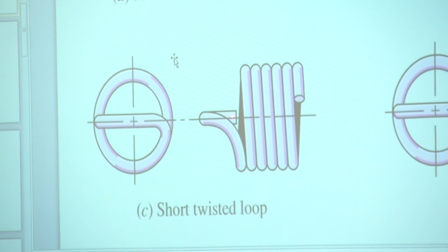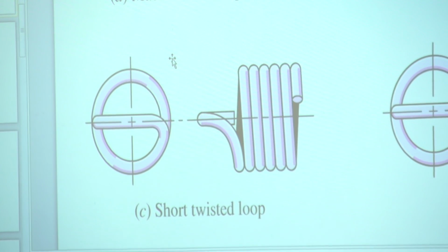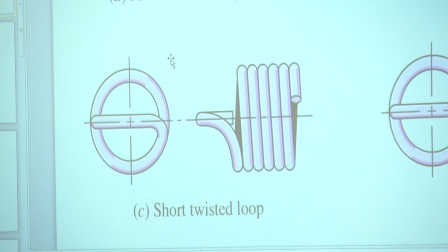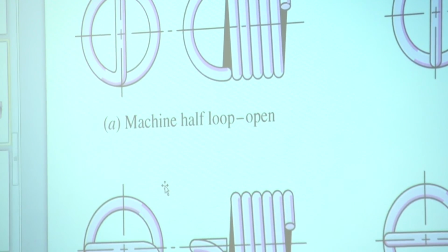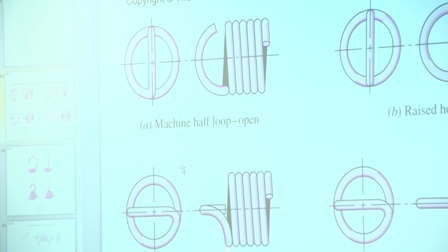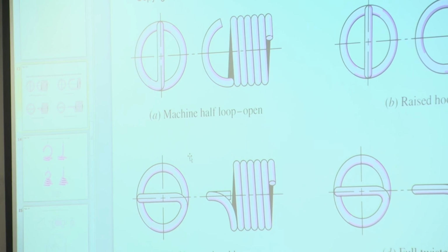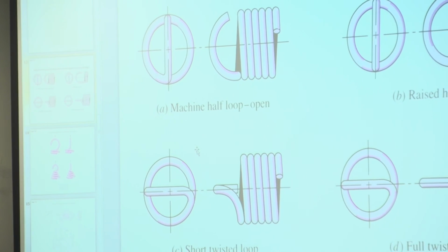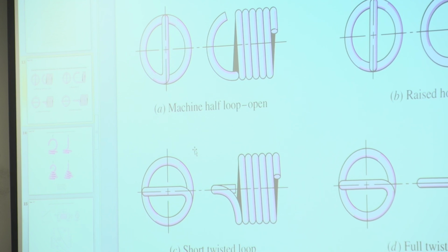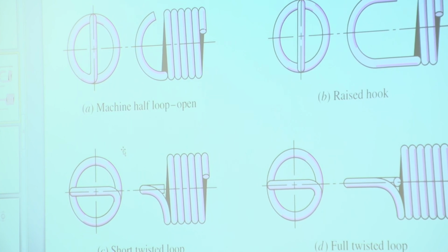There's a curvature here, right? Right over here. See that? That curvature is shown here. Agreed? That's one curvature. There's another curvature over here. So this thing curves like this, and then it twists like that. It's a double curvature. And you have to check other factors than the shear stress in the body of the spring. For example,